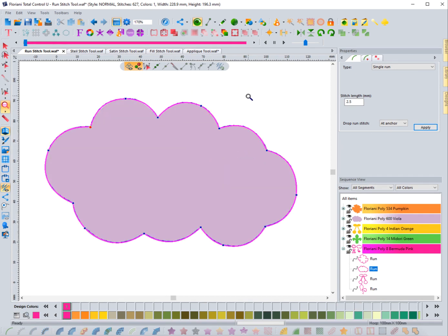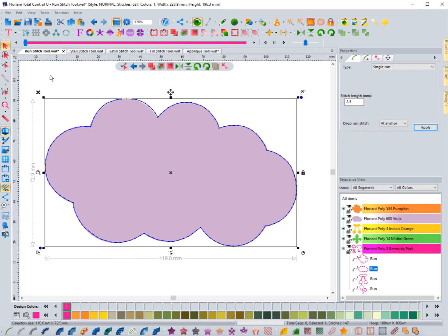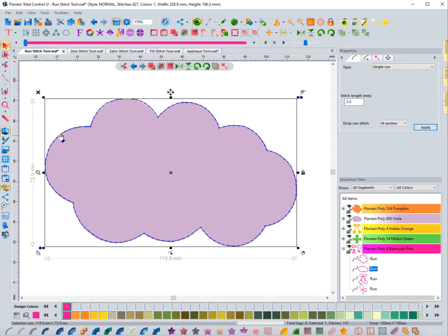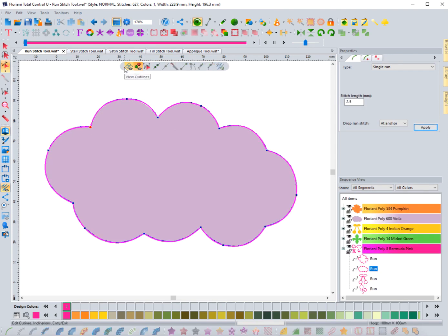If I zoom in here, you'll see that I can move the lines around. I can bend the shapes using these handlebars. The only time I can access this form of editing is using the shape edit tool. If I click on the selection tool and I go back to the original thing, you'll notice that the edit tool isn't right here. But if I select this, notice that once it's selected, the shape edit tool comes up. So you can access it right here from the floating toolbar. And notice that once I did that, it changed again.